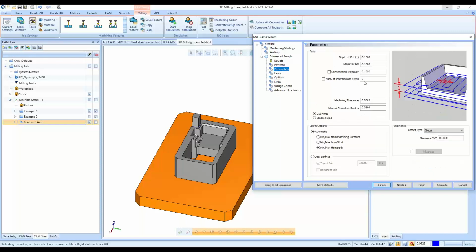When we go back to our depth of cut of 150 thousandths, we're going 150 thousandths step by step. If this surface here doesn't line up at 150 thousandths, it's not going to know. We'd have to go back in and do another roughing operation or do a planar operation to finish off this surface, to finish the depth going down.